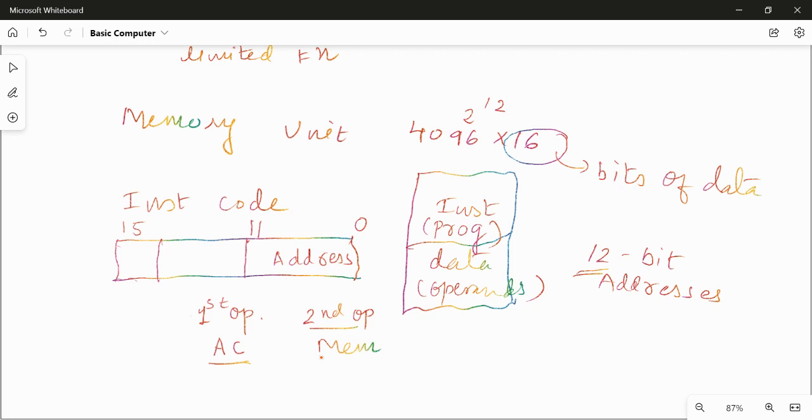First three bits in the second part will specify the exact operation to be performed through the instruction. So, the operation code, also abbreviated as opcode, will be specified in the second part of the instruction. The width of this opcode will be 3 bits. That means bit numbers 12, 13, and 14 will be available to specify the opcode.